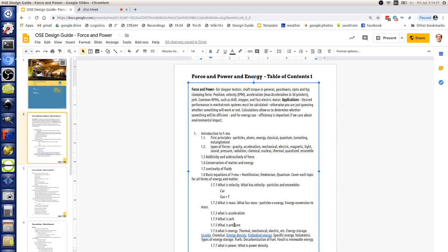Pressure is relevant to things like a rubber tire. For example, if you want to know how far a tire will deflate under a tractor, you can say, okay, I've got a certain pressure, which is pounds per square inch. Well, if it's, say, 50 psi, how many square inches do you need to sustain that? So basically your tire will flatten out to that number of square inches that corresponds to the force of your entire tractor. So typically say we inflate tires to 50 psi or whatever, well, you can actually get a feeling for what that quantity will be based on the weight of an object.